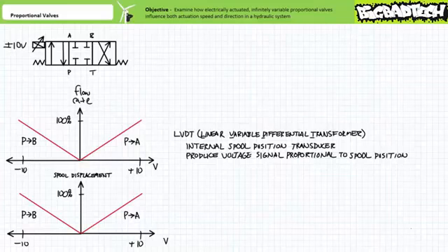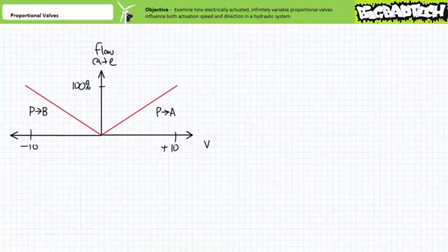Note that not all proportional valves include positional feedback mechanisms like LVDTs, especially for low-cost applications that do not necessitate precision. As previously mentioned, in ideal, perfectly linear and predictable circumstances, assuming a range of positive to negative 10 volts, the application of 0 volts perfectly spring centers the spool. Positive 10 volts results in full flow in the straight-through P to A direction, and negative 10 volts results in full flow in the cross-connect P to B direction, with the intermediate positive and negative voltages resulting in perfectly proportional intermediate flows.